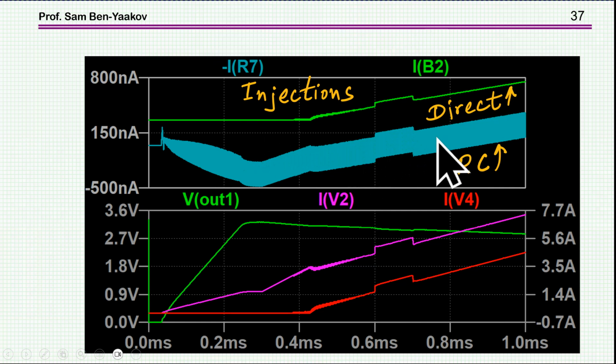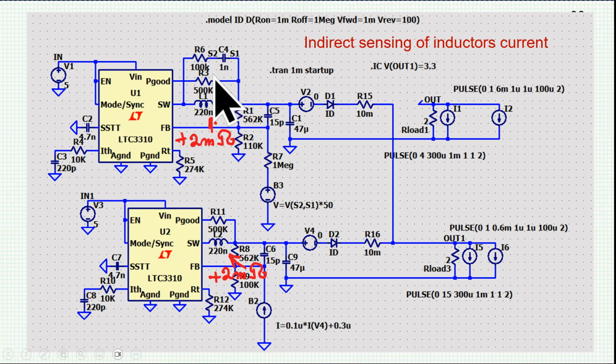Now, the injection of this signal with the ripple in this particular case does not cause any big problem, because it's a very high frequency ripple. The switching frequency of this converter is 2 megahertz. Now, the bandwidth of the control is much, much lower than that. So therefore, it doesn't make a difference. Actually, it's been filtered out, and what the controller is really seeing is an injection like this. So you can use this idea.